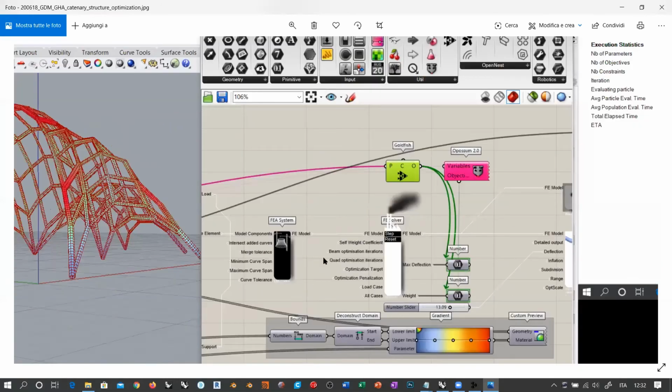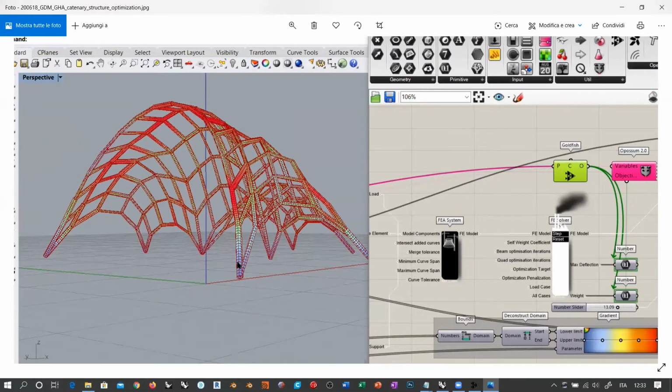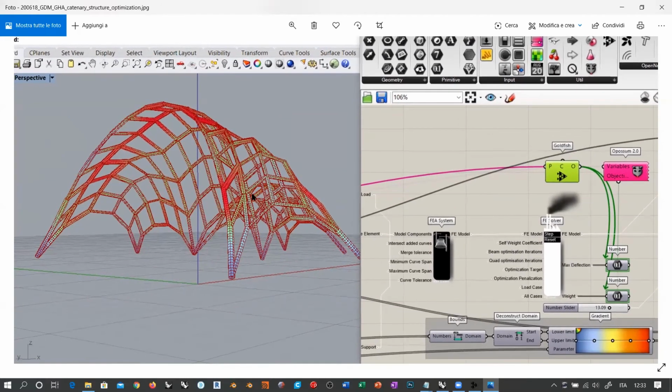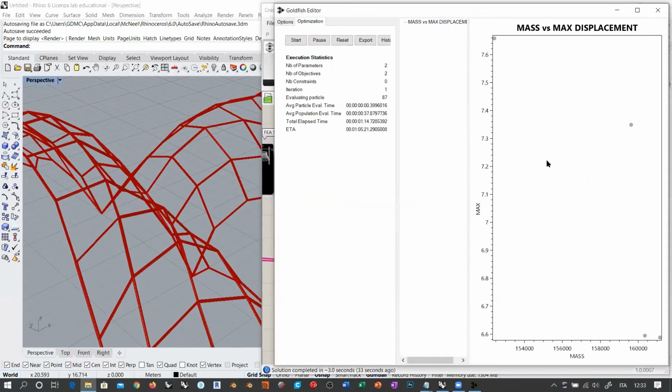It's not visible here in terms of thicknesses, but you might recognize that these elements here are thicker than the upper elements here at the top, of course. Okay, so this is the result that we expect to obtain from this optimization process. At first, of course, the thickness would be randomly distributed, but as long as you leave this running, you will get to a much more refined result, which tends to have thicker elements at the bottom and thinner elements on top of these dots, of course.